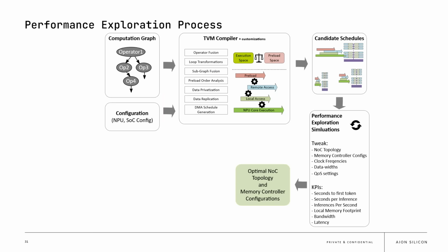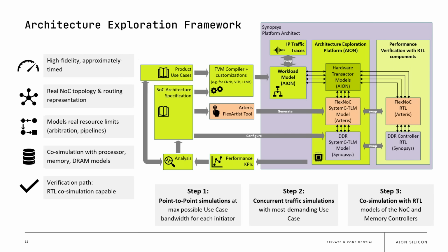Part of the performance exploration simulations is the SystemC model of the interconnect, which is generated by the Arteris FlexNoC tool. Now FlexNoC is the UI which the designer interacts with to configure the NoC. So out comes the SystemC model, and that is combined with a model of your memory controllers, of which there could be many.